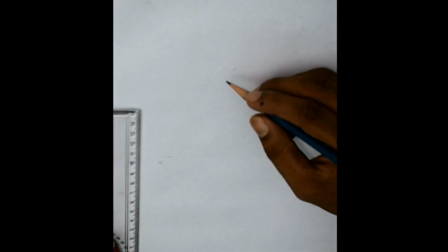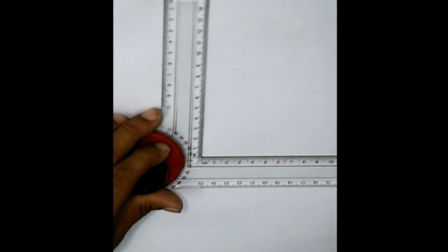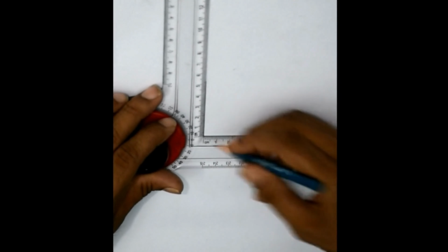So first I will draw the xy line here. This is our xy line, and as we have seen, this 100 mm line is perpendicular to the HP. So it will be a straight line in a vertical manner, and it is mentioned in the question that it is 20 mm away from the HP. So this is important, first thing, and the line is 100 mm.